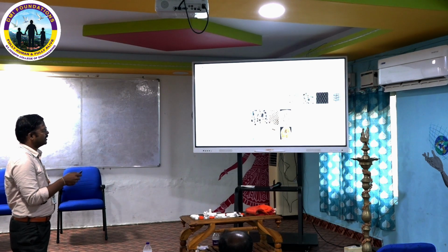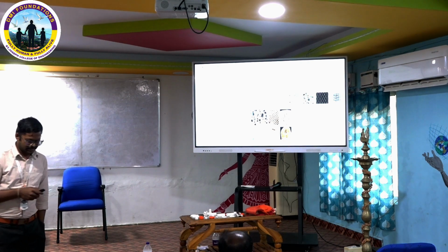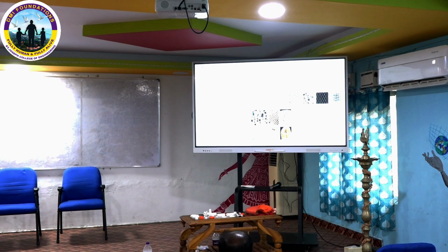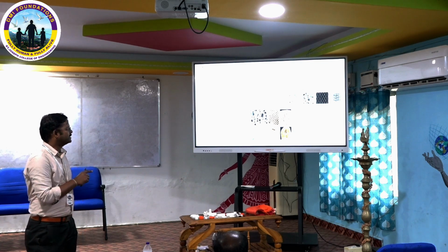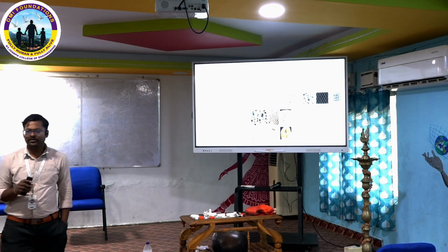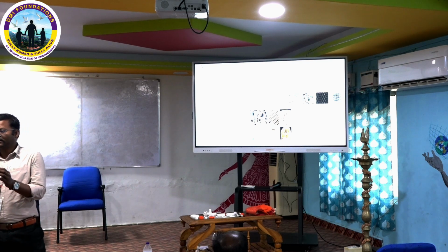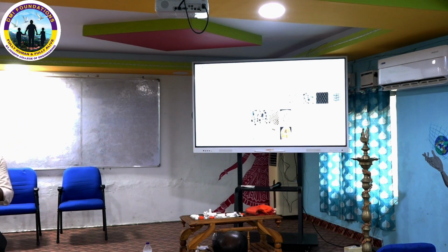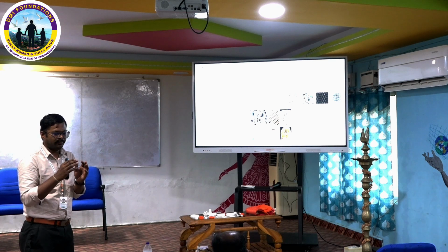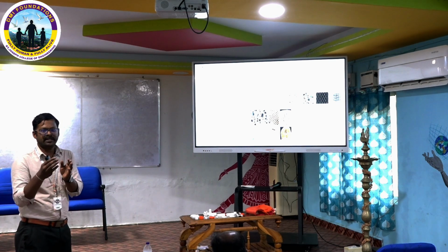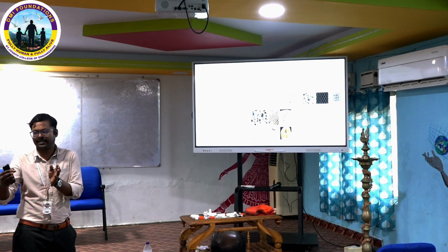First of all, you can see the top corner slide. It is the category of cellular structures. We commonly have two categories: one is stochastic, another one is non-stochastic, which is called lattice structure. First one is foam, which has unit cells populated throughout its overall volume in a random manner. It doesn't have a periodic manner. The unit cells are populated randomly. There is no arranged pattern.